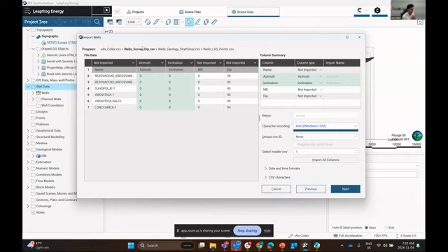This constructs, again, the 3D trajectory, where we need to define the well ID. Again, this is how the relational database works. The caller locates it in space. This survey creates the 3D trajectory from that point in space. So we've got an azimuth of 0, an inclination of 0, and a depth of 0. All of these zeros essentially create vertical wells. If you had a deviated well, you would notice that the azimuth, inclination, and measured depth would be populated with much more information.